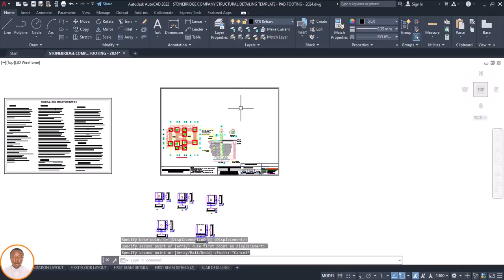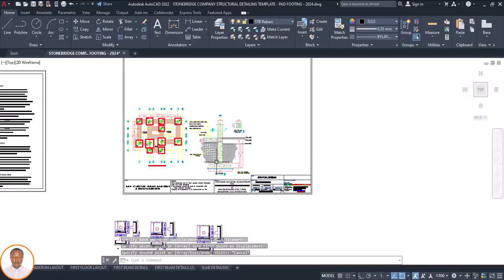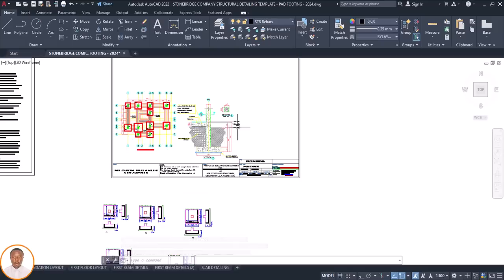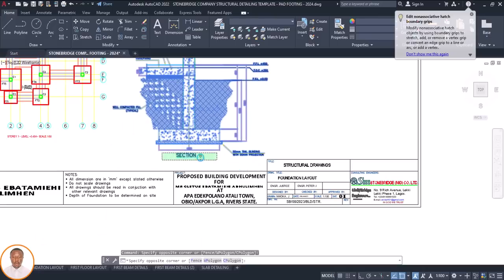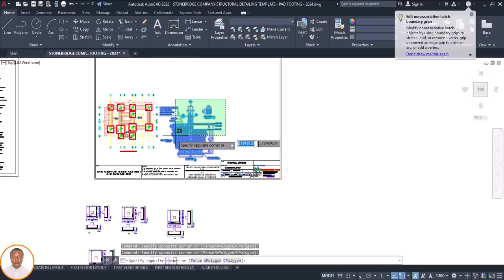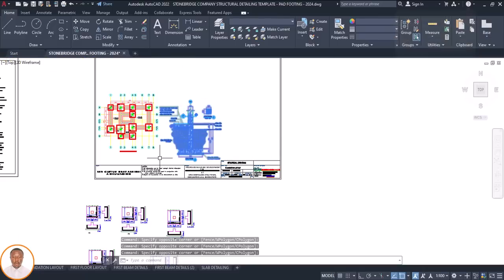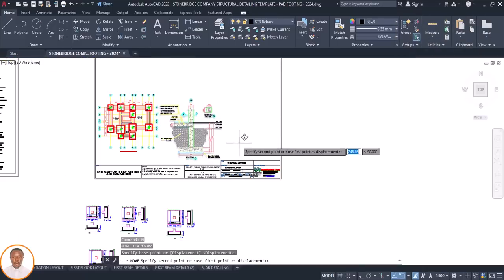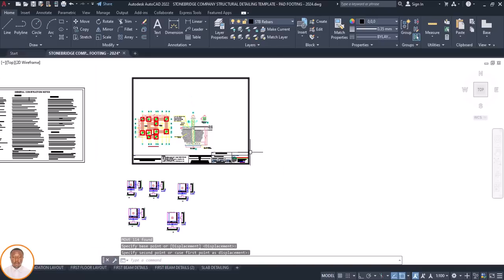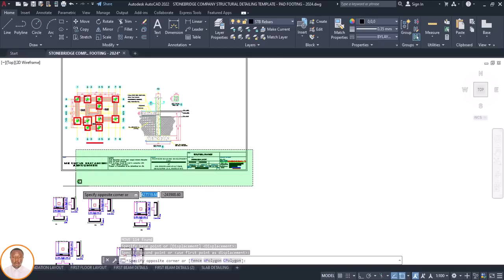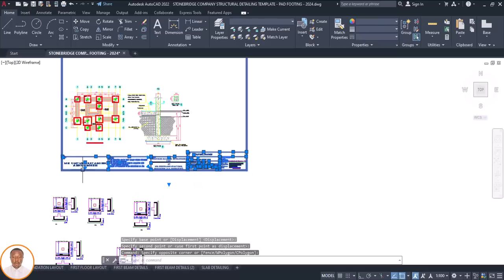So now you can see that we have XX. Is that okay? SS here. So all I'll do is, okay, let me do something here. Okay, it's better I explain very well for you, so that enter. Let me take this one up a little. Good, fine. So then I will now click on this one, select this one as I've selected. Then you now press what? Scale. That's SK, scale, enter.